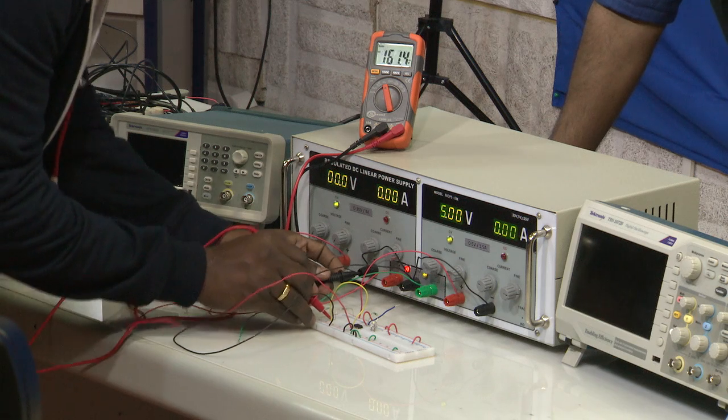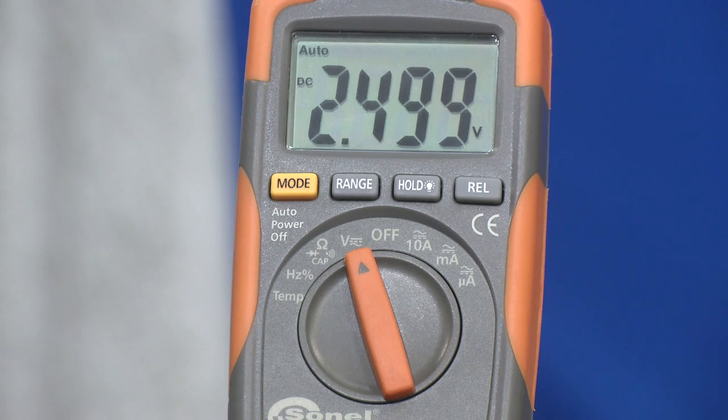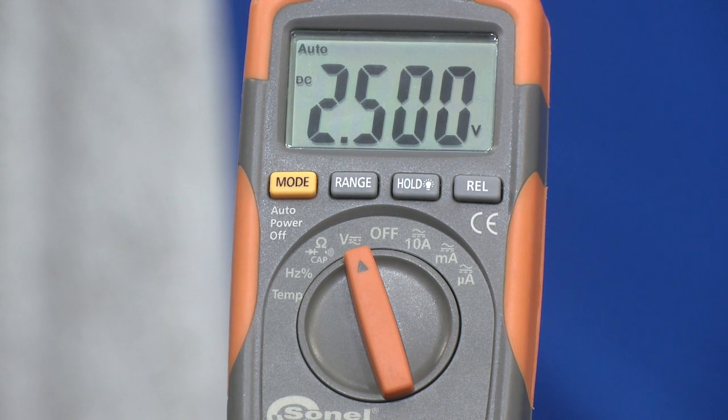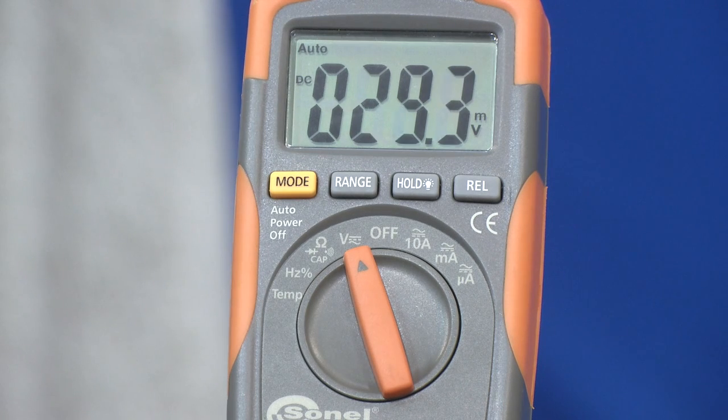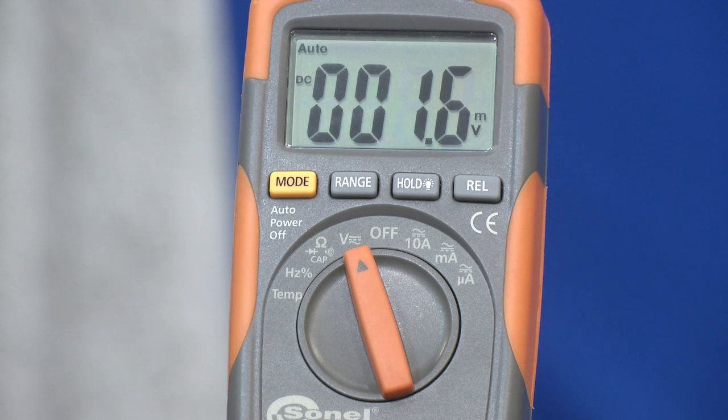So, if you see in the multimeter, you can see the voltage is about 2.5 volts, excellent. That means that the resistors he has selected this time are extremely accurate, having the same value with minimum tolerance, right. That is why we see 2.501. So, that is good. So, 2.5 volts we are applying across the inverting terminal.